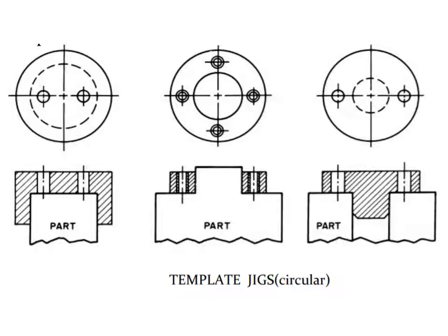And once the jig is located on the part, the distance x is accurately marked on the jig, and the hole is already made there, and this hole will act as a guide for the drill. If you make the hole along this already made hole, considering that as a guide for the drill, it will reproduce the same hole onto the part with the same accuracy already built into the jig.